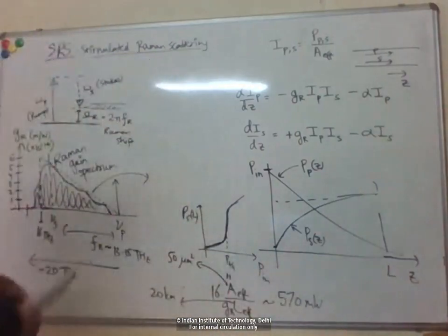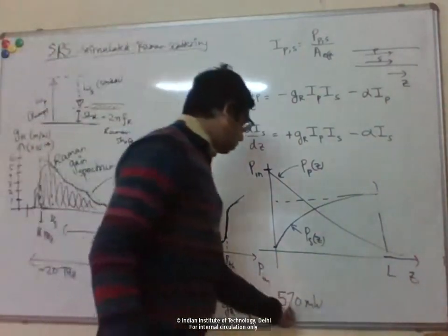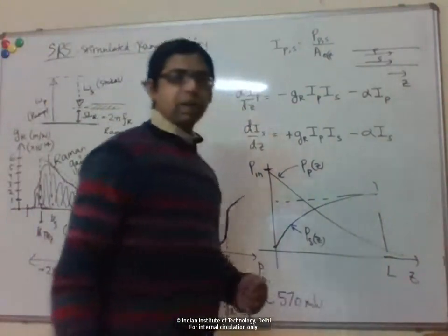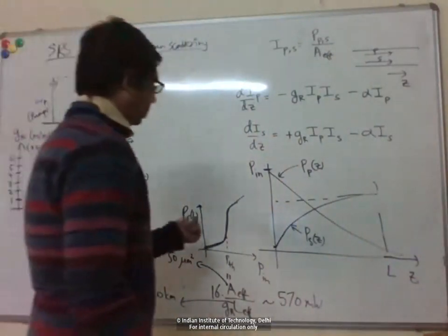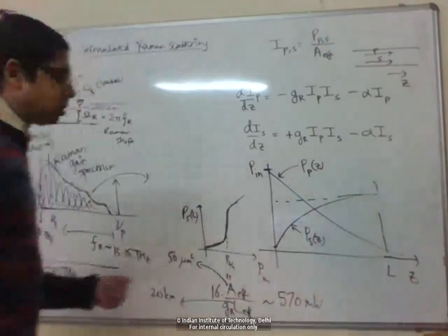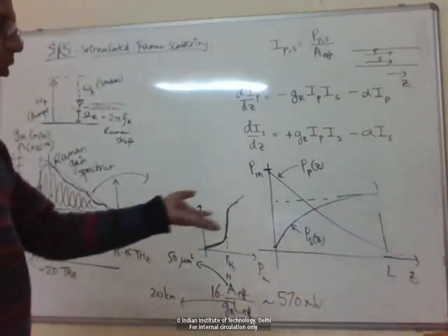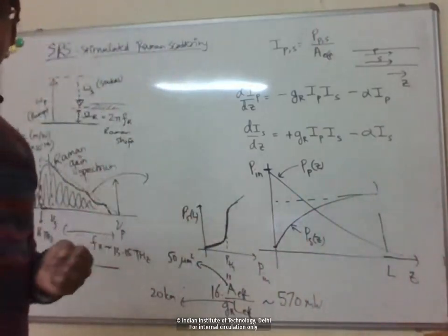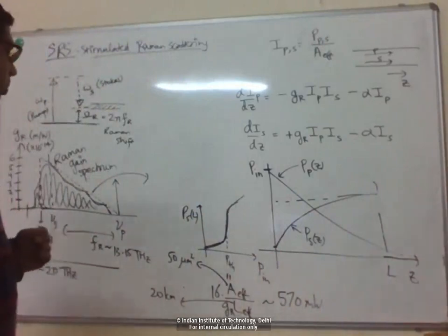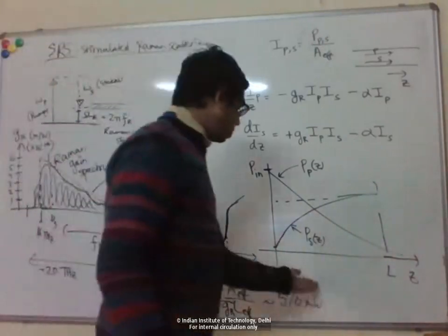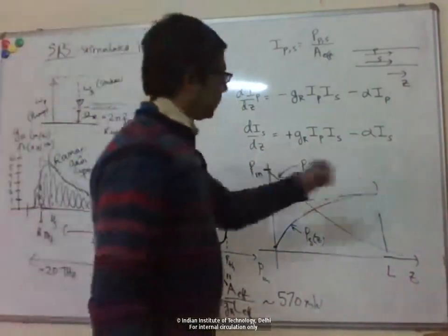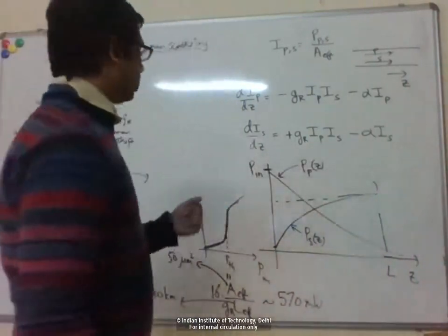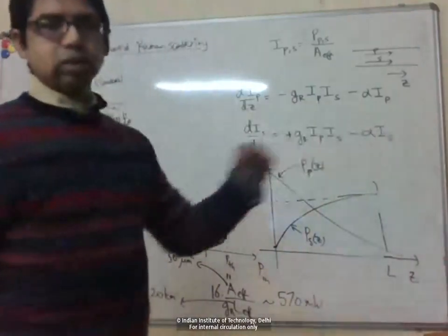Right, so you can see this is now a very large amount of power here, 500 milliwatts, and typically, as we discussed last time, the powers that we use for optical communication are in the tens of milliwatt. Okay, so typically we are much below this threshold for Raman scattering, where we transfer half the power to the Stokes.